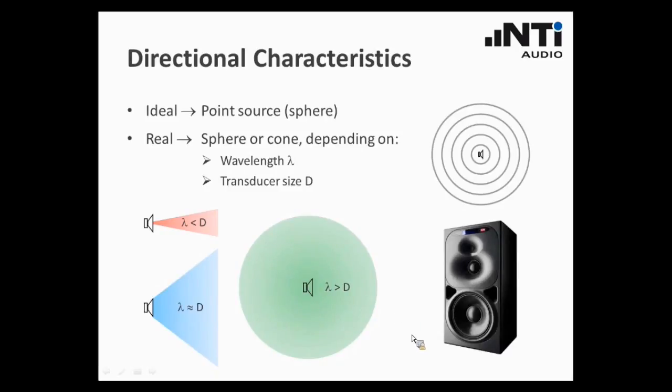Well, if we look at a concrete design of a three-way speaker here, for instance, you will notice that the high and the mid-tone speakers have been installed in a cabinet with a specific shape. And the reason for this shaping is that we want to achieve a controlled coverage of the sound field. We want to achieve a consistent frequency response, not only on the mid-axis, but also in the whole region here. The woofer, however, you don't see any specific shaping of the cabinet, and the reason is quite simple, because as shown here we have pretty spherical radiation anyway.